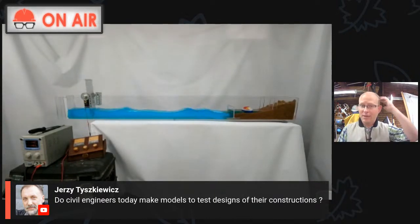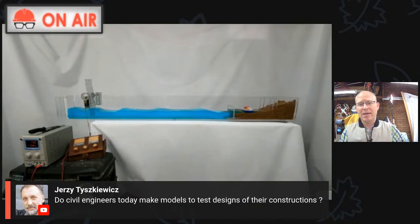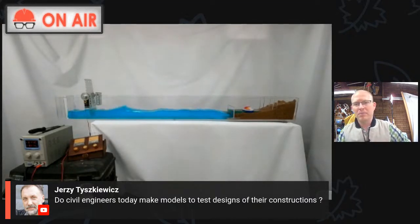Another one is wind, especially for tall skyscrapers. A lot of times you'll build a wind model because the flow of wind around all the other buildings is really complicated to characterize on a computer. And so a lot of times to estimate wind loading on a skyscraper, they'll build models.